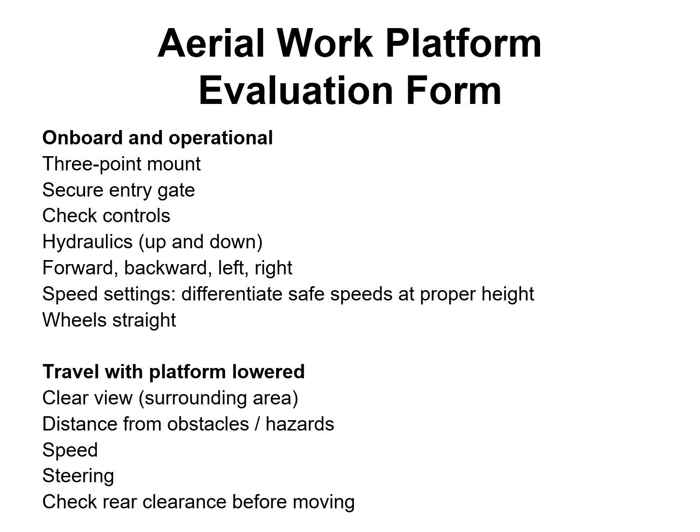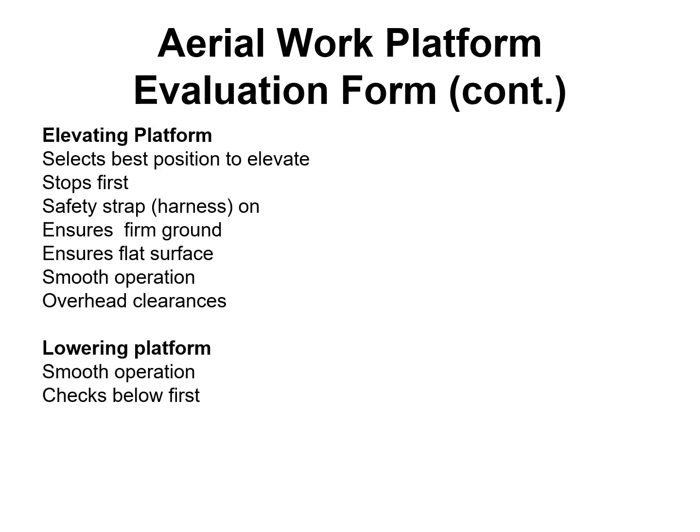Wheels are straight. Travel with the lower platform lowered. We want to make sure that we're lowered when we're traveling. We want to have a clear view of the surrounding areas. We want to ensure distance from obstacles, hazards, ensure speed, steering, and check rear for clearances before we move.